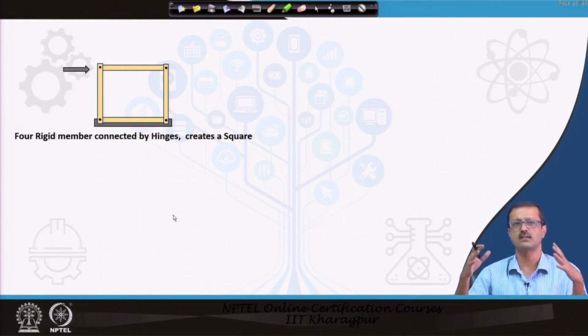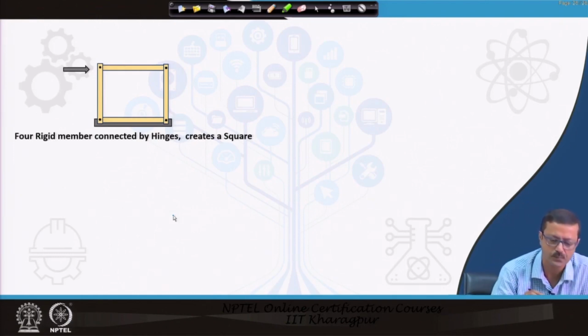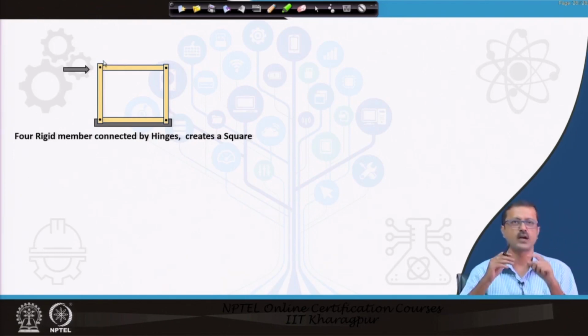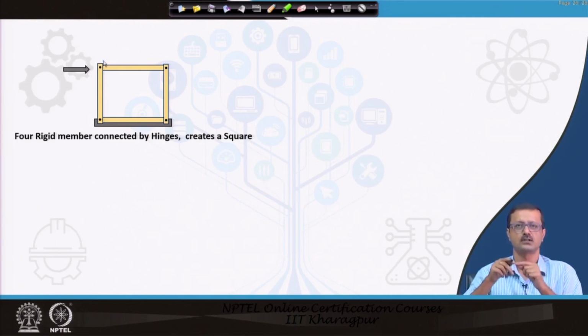If you see the truss, it is all triangles, small pieces of triangle. Why is it a triangle? Why not a square, or a pentagon, or any other shape? Let us discuss why the triangle suits best in load resisting. See, I have drawn here 4 bars, and those 4 bars are pinned. Suppose you imagine there are 4 ice cream sticks, joined by 4 pins, like an office pin or something like that.